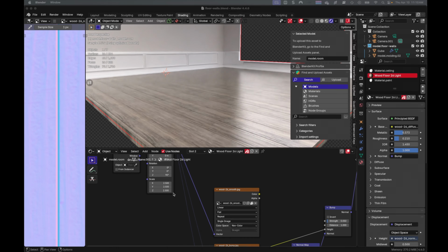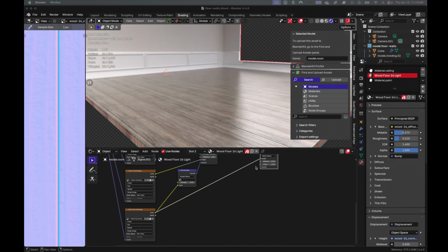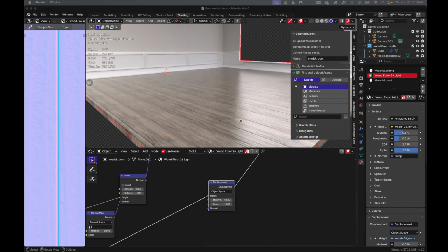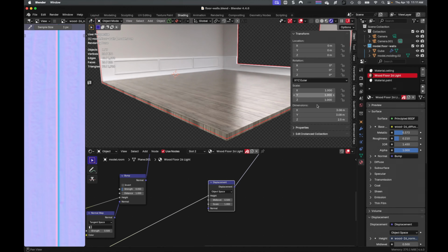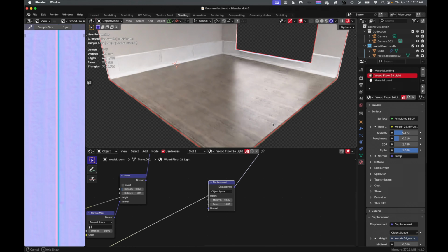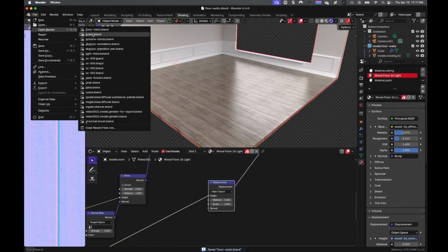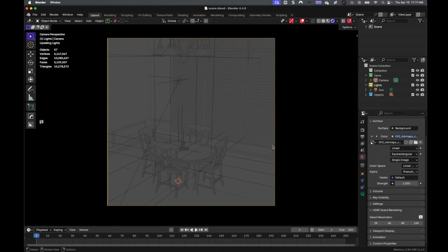Right now, I moved over to the floor. I noticed in the last shot that the floor looked a little muddy. So I went back and opened up the floor-walls blend file. I'm no longer in the scene file. I'm in that original file, making some changes to the shader of the floor. If you remember, we pulled that in with BlenderKit, but I'm going in and manually making some tweaks on it. So when this sunlight hits that floor, I want two things to happen.